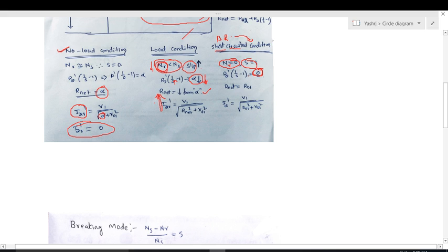That's why the net resistance is nothing but R01, which is approximately equal to R2 dash. Some resistance is there, so at this condition the rotor draws maximum current. Under block rotor condition, the rotor draws maximum current and maximum copper losses take place.